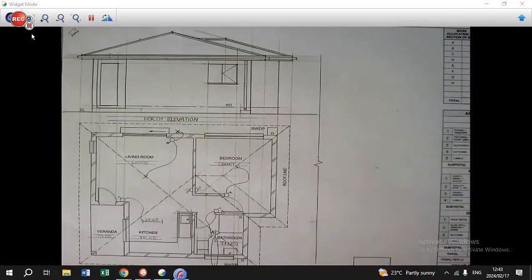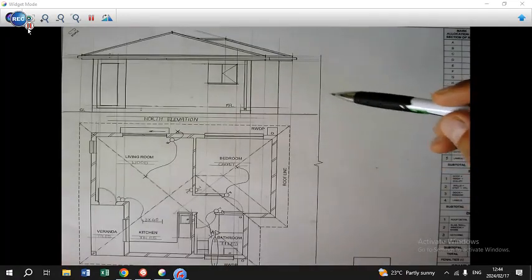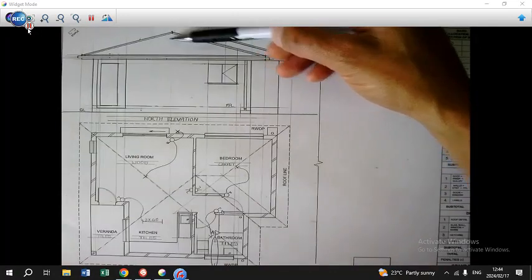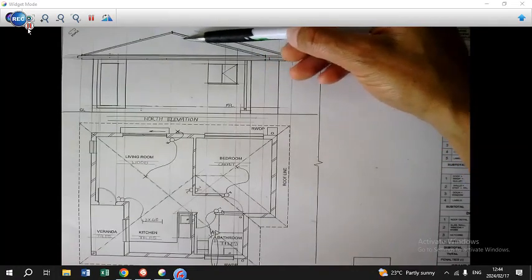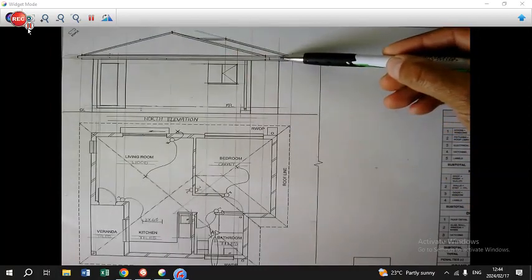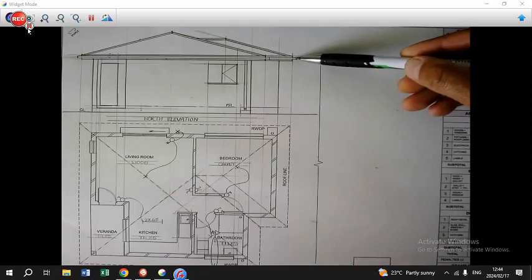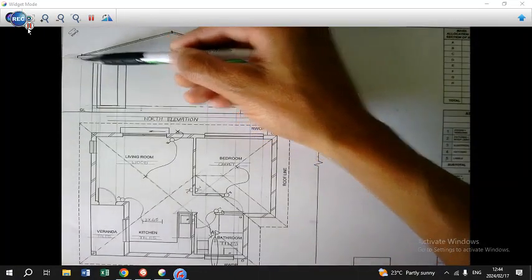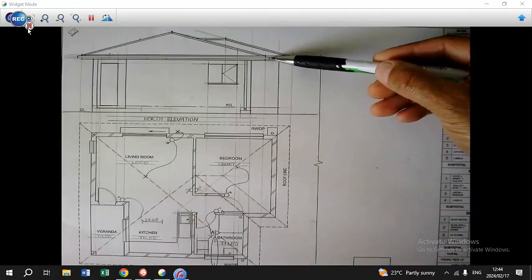Grade 12, we have concluded the north elevation and we have implemented all the features and components as indicated in the instructions. Just keep in mind that our roof lines are double lines in all the different cases here. We have our fascia board that has 4 divisions, of which 2 on the inside will be our gutter. Our gutter extends 3 millimeters past the end of the fascia board, and that allows for the gutter to be returned on the side. You will see that it returns here as well, so that distance out will be 3 millimeters. Of course, we have our downpipe here that goes into our gully.